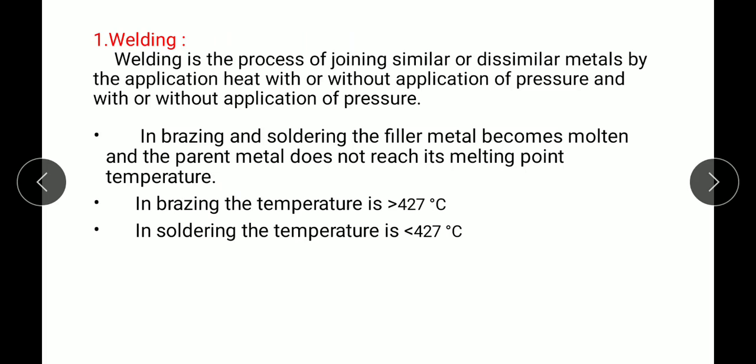When considering this joining process, we have two other processes, that is brazing and soldering. Brazing and soldering are also similar to the welding process, but here the filler metal temperature is below 500 degrees centigrade. While doing brazing and soldering, the parent metal does not melt because the filler metal temperature is very low.